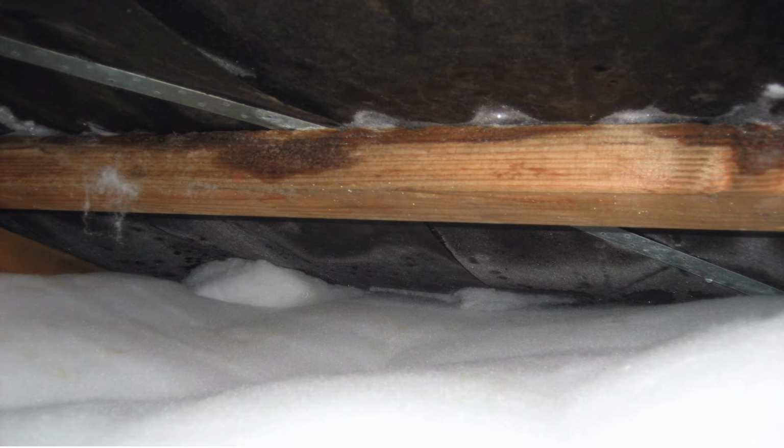The ability of materials like underlays to absorb water, which is what underlays are there for, particularly kraft paper, when that gets exceeded by the amount of moisture that accumulates, then that water's got to go somewhere. And it might go into the framing where it will do damage over time. If it sits around long enough, or even if there's enough humidity in the air where we've got metal fixings, that's going to lead to corrosion and other issues as well.